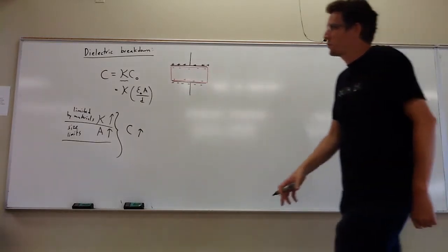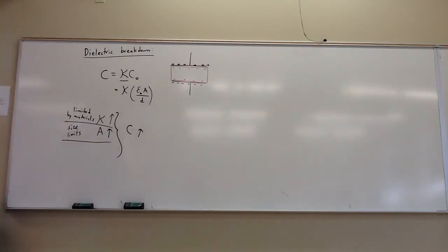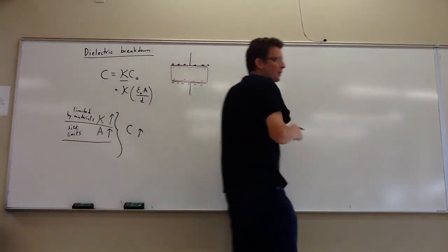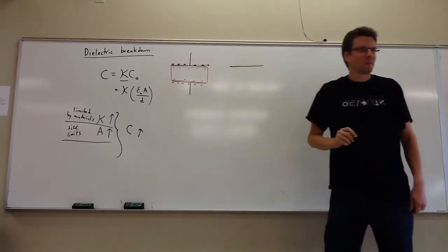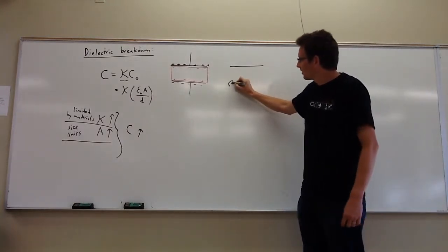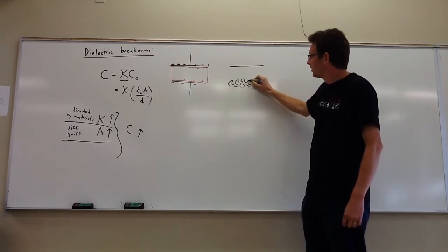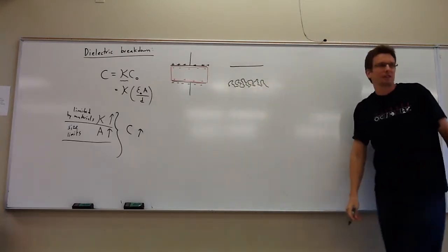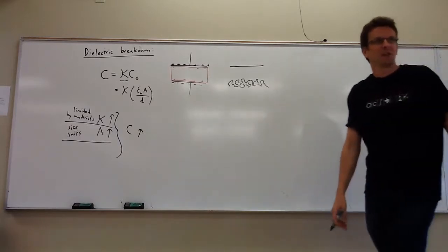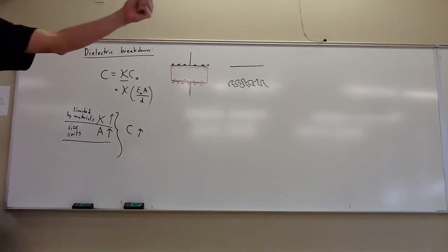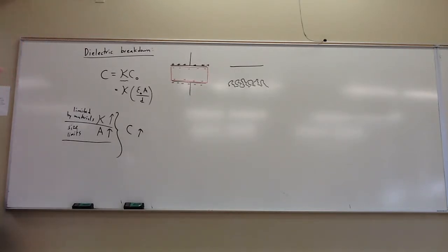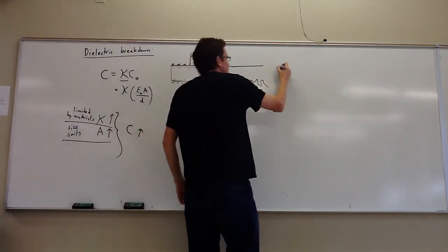Now, I'll tell you there's a trick that they sometimes use in capacitors to fit a very large amount of area into a small volume. Okay? So what they do is that they are not really parallel plates. One looks like this. This is a more advanced capacitor where the plates aren't symmetric, but the other one is like this. The surface area is tremendous, but they also pack it into a very small volume, right? There's lots of crinkles and folds. If you actually pulled it out straight, it would be a massive area, but it's crinkled into a very small space. These are your electrolytic capacitors.